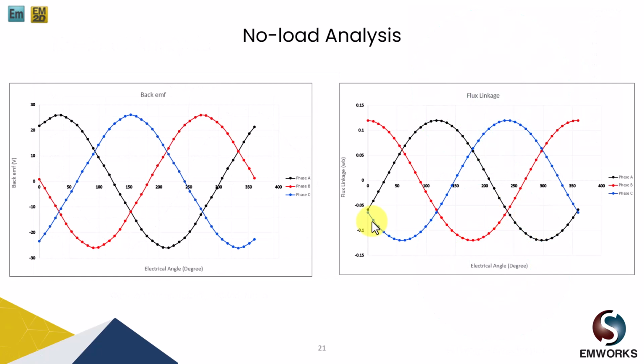So finally we obtained its back EMF and flux linkage, and now we see here that the back EMF is not perfect, but it's very close to sinusoidal, and it may also contain some small harmonics, but overall the THD of this third model, where we have used a magnet ratio to pole arc of 0.5, leads to a sinusoidal back EMF, and also the flux linkage is almost the same as the other two models.